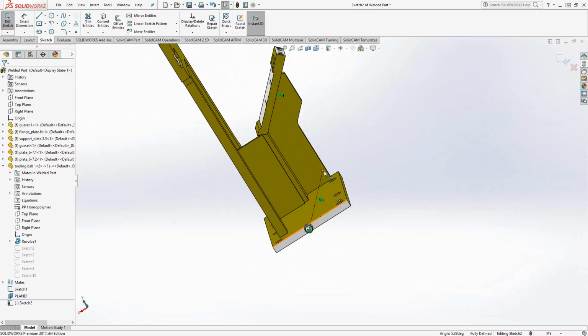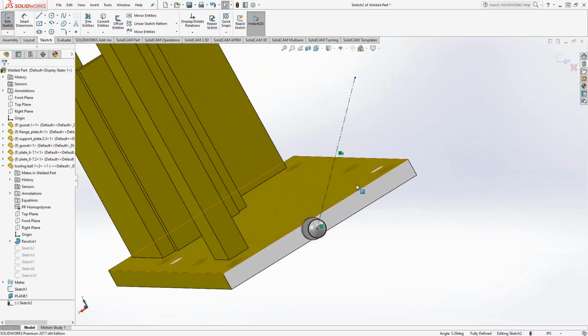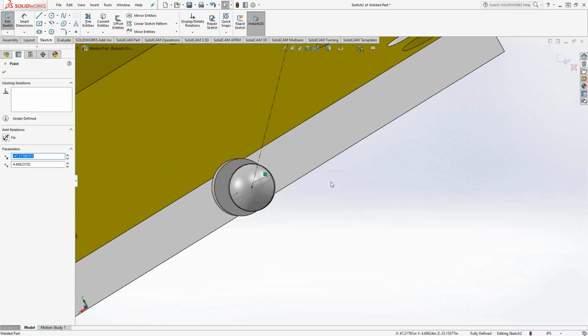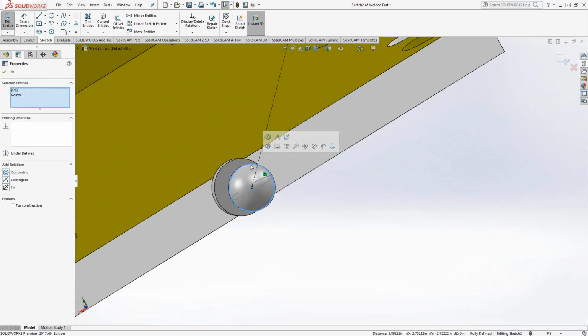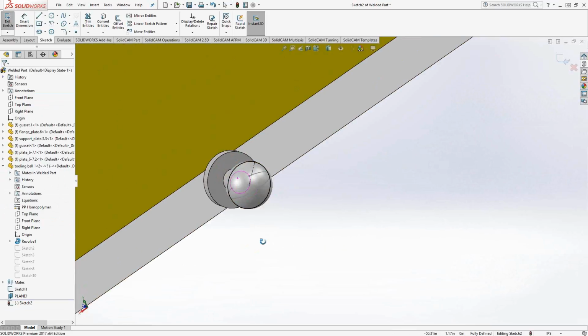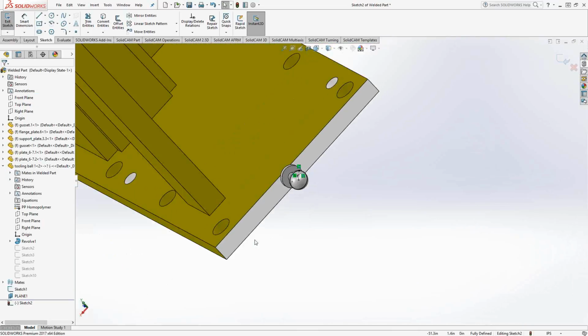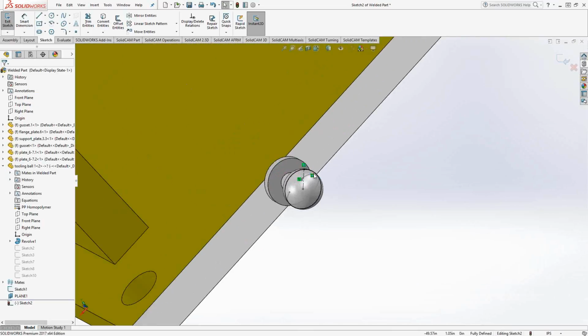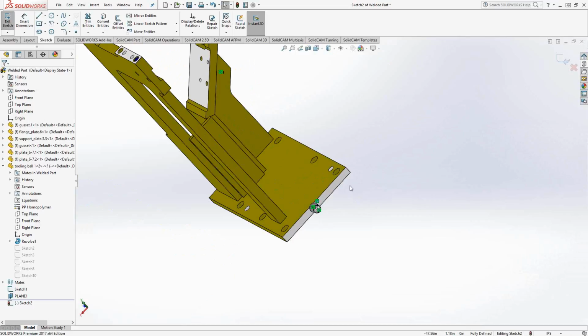But we're not actually touching off anywhere in space there. We're touching off on the ball. So I'm going to do a relationship between the endpoint of that line and the circle sketch. And I'm just going to say, make the endpoint of that line coincident. And by doing that, I've added an endpoint to that line that is actually on the tangent point of that circle. So in real life, when we go to touch this thing off with whatever kind of indicator we're using on our machine, we'll touch right on that point right there. That is the topmost point of this sphere at this angle. Okay.